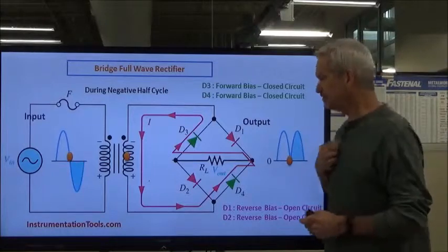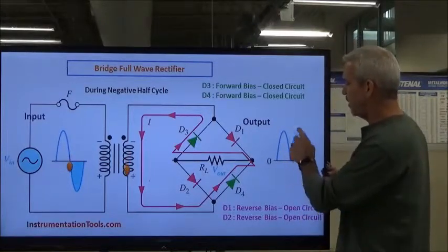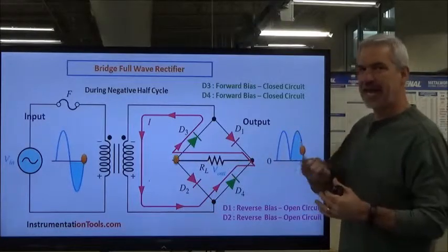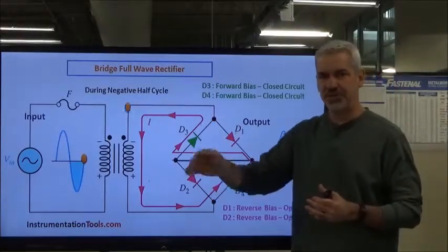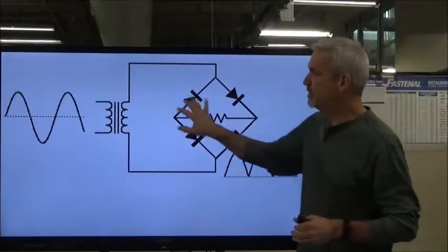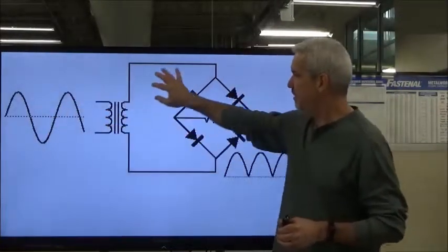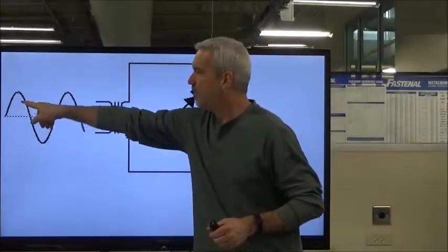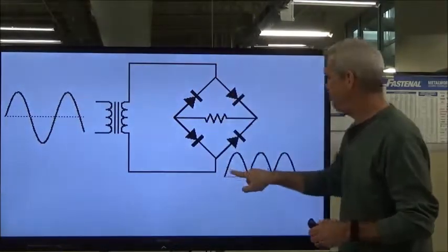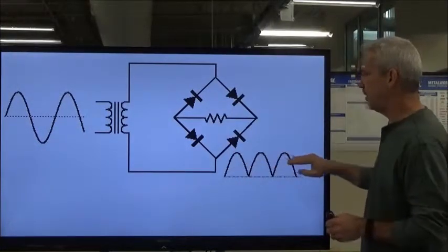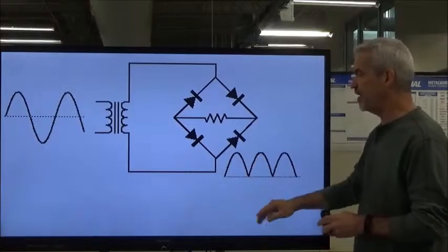Okay, so we've got these two humps right here, and while they are DC, we can't have that kind of variation in our voltage like that. Okay, we've got to have a smoother ripple. But anyway. This is the symbol. This is the rectifier itself, and we take the alternating current, and we wind up with a DC or more of a direct positive current only, and nothing on the negative side.